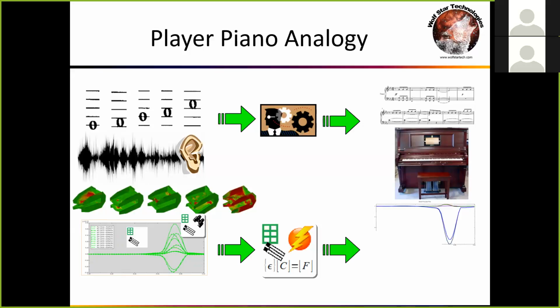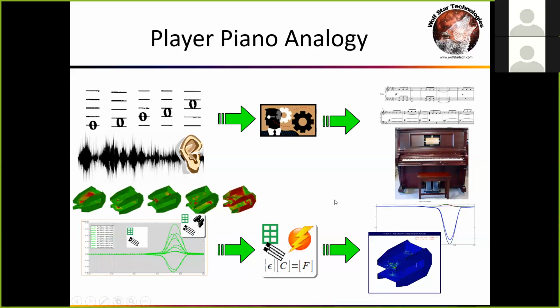These time histories of loads are basically how much each one of these unit load cases participates in the full field response. So essentially, we can take that and play back the time history of loads to reproduce the stress and strain events on the entire part. Those of you who are familiar with the concept of modal response analysis and modal decomposition, this has a direct parallel to that approach. It's not the same mathematics, but it's a parallel set of mathematics as modal decomposition on a structure. Okay.